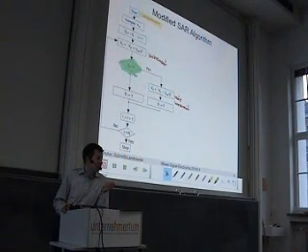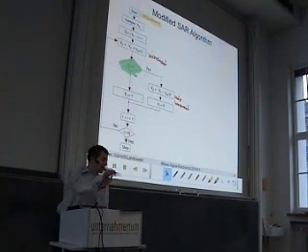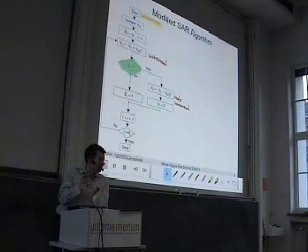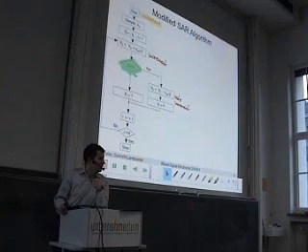So if you build a comparator which compares always against the same reference, then this is considerably easier than building a comparator that compares against a variable signal. This is due to the signal levels that your comparator has to fulfill.